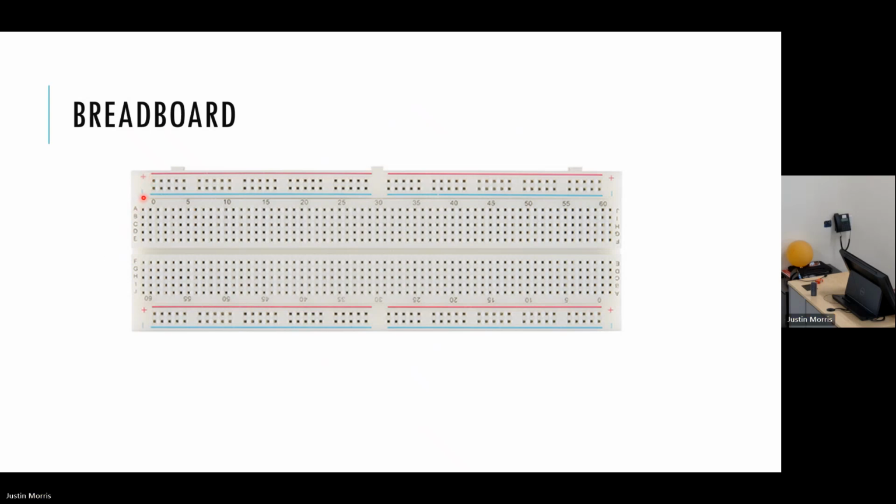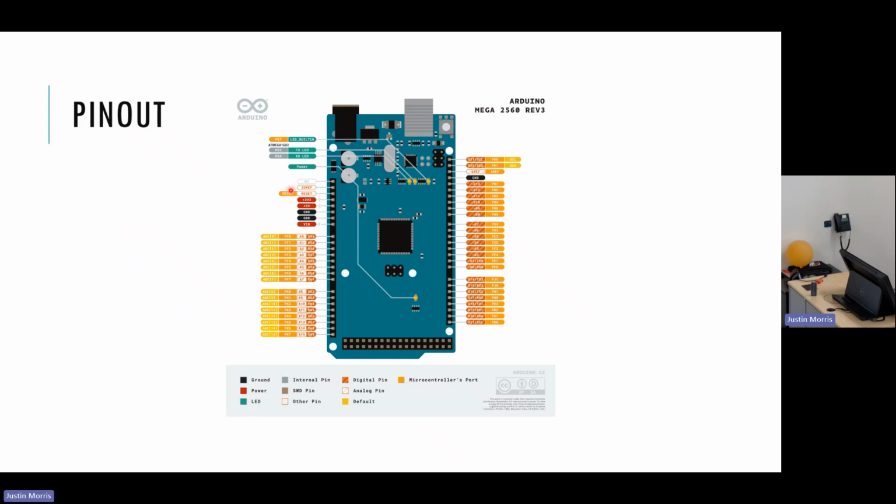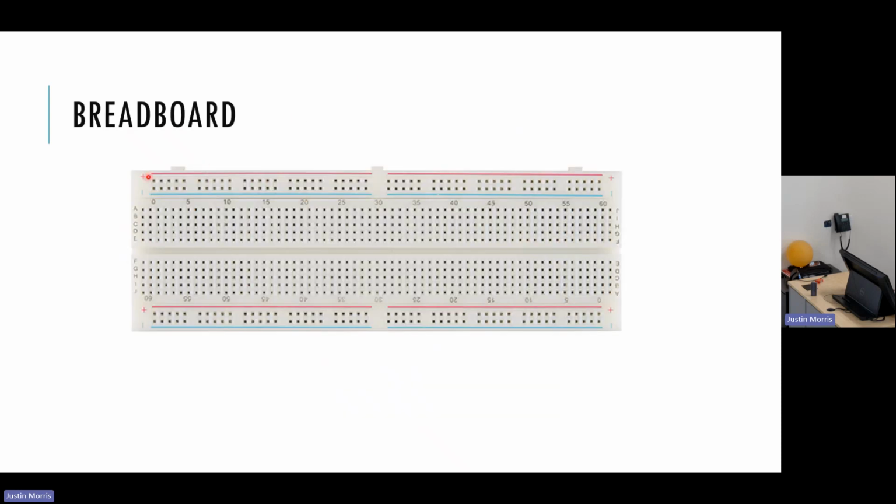And the other thing that is usually standard practice for the breadboards are these, you see the plus and the minus. So those are for usually powering your devices. So you'll usually connect ground to the minus, and then from say the Arduino board, you can grab 3.3 volts if the sensor is requiring 3.3 volts, and you would connect that here. And then all of these pins on this line are all connected to each other. So if you need a sensor that requires power, you just connect the sensor to the power lines here. And then there's also usually 2 of these for breadboards because maybe you have one for 3.3 volts, one for 5 volts.